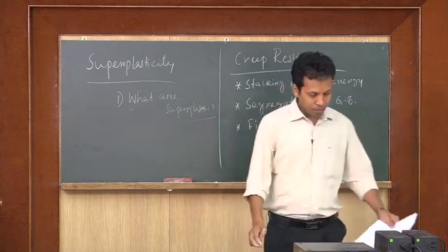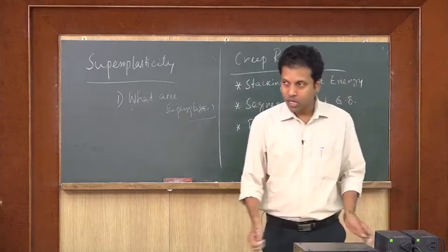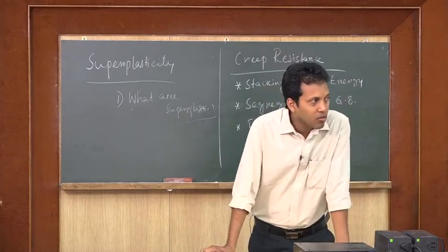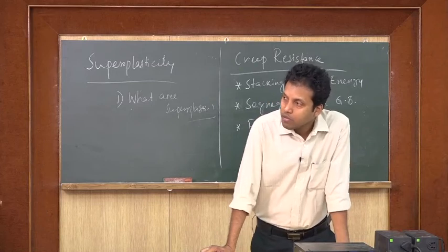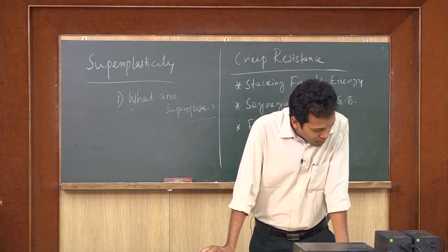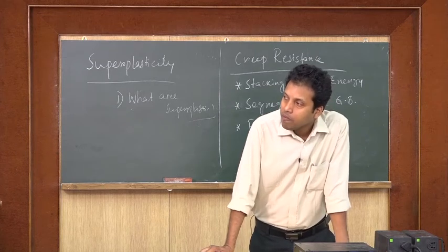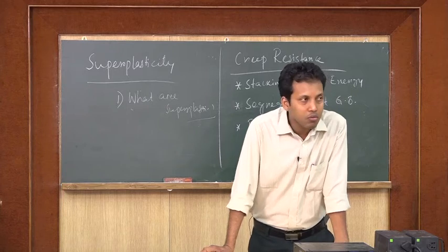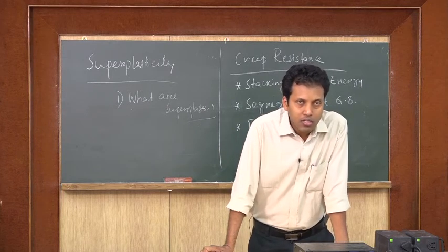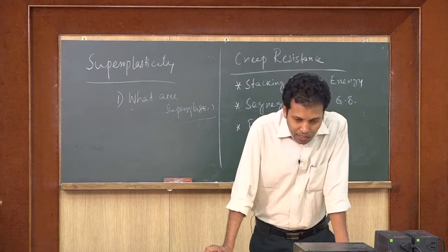Here one term, stacking fault energy, which you heard earlier, helps. If I can reduce the stacking fault energy of the material, then it improves the creep resistance. How does it work?